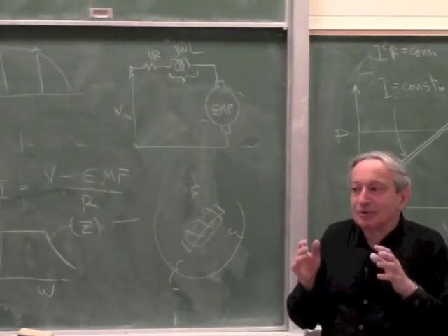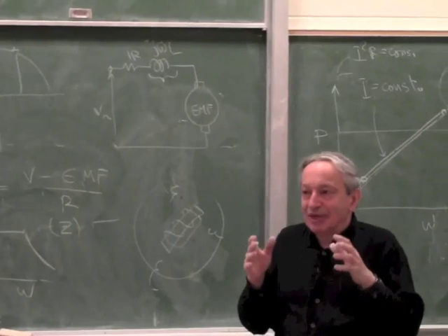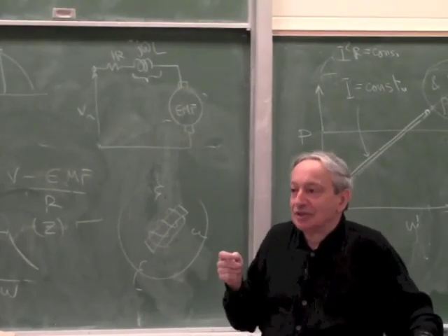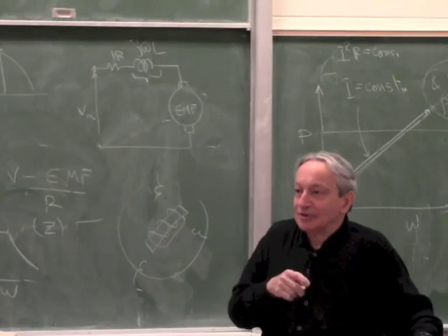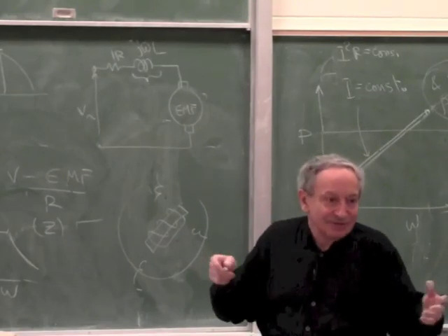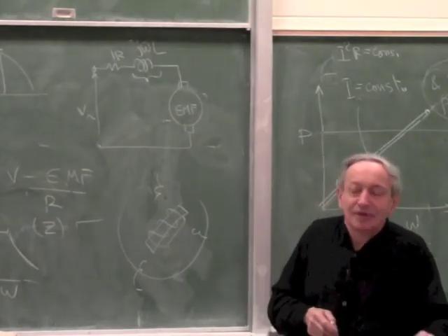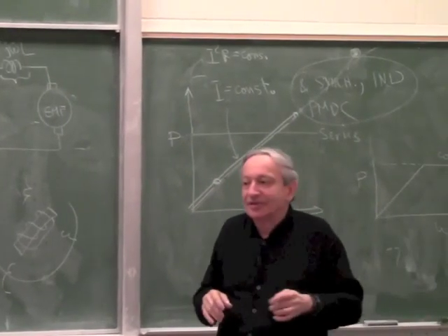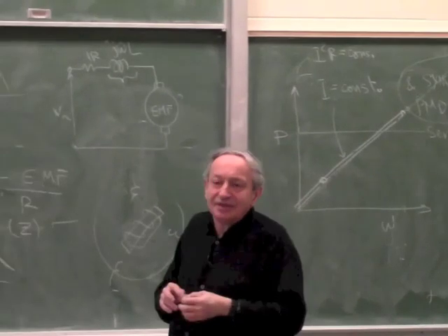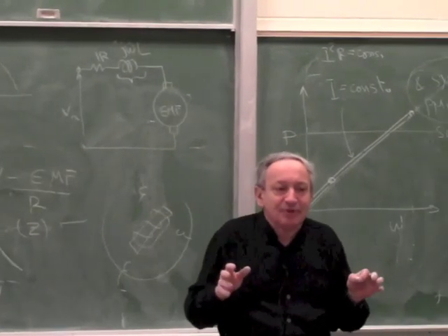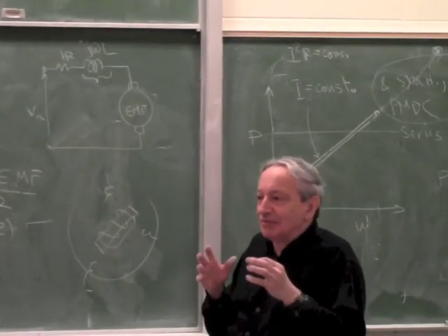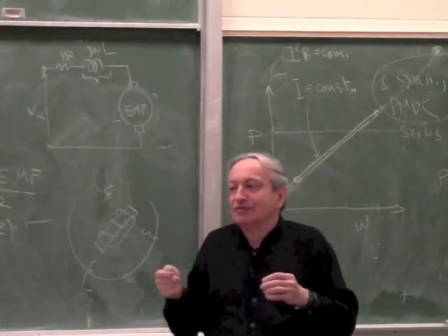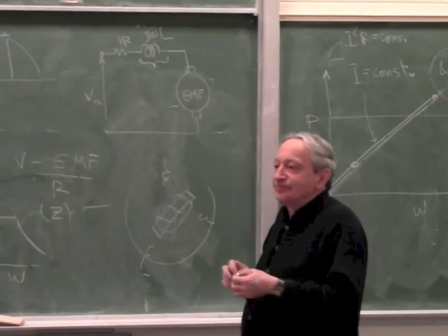So the power of the motor doesn't change. If you make a motor with fewer turns and heavier wire, it has less voltage, but more torque. So the torque times the RPM is constant. You can gain some power by running the motor faster in a smaller package, but very crudely speaking, the power doesn't change very much. You can play around with the current and the voltage on the coils.